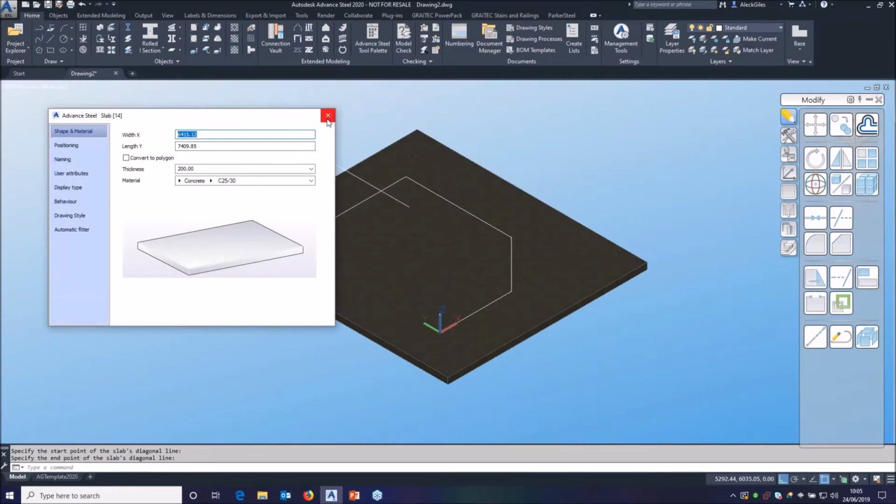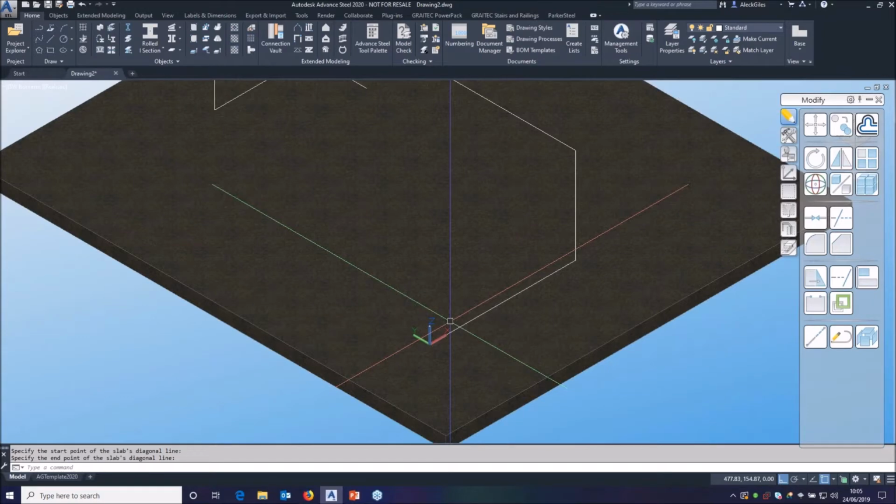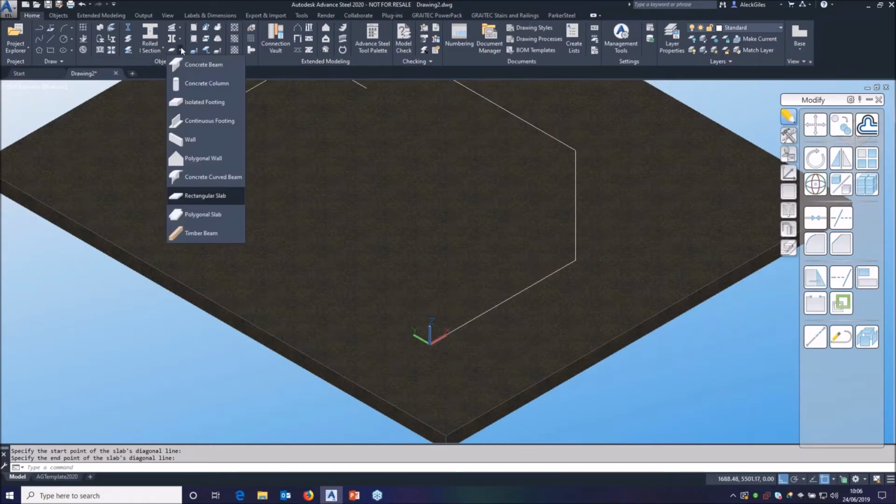There we go. Now for the stair, we see people do this as slabs, sometimes as beams, but they don't seem to ever quite do it the way we would recommend. What's the fastest way? We need to use beams, because then you can put the railing straight onto a beam. So you definitely don't want to be using slabs in any way.